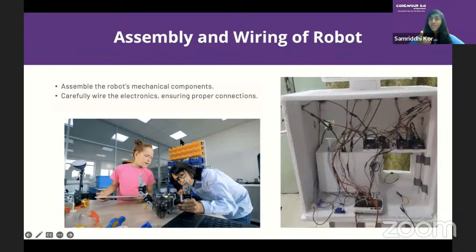So first, I'll build the fire extinguisher. It works. Done. Leave it aside. Take another microcontroller. Then on top of that, you can build your safety lock. That works. Then take another microcontroller. Build your DJ. And once after everything, combine it into a single microcontroller, combine your code, execute it. And that's when you can get an error-free, easier way to build your project without many messy wires when you're trying to debug stuff.